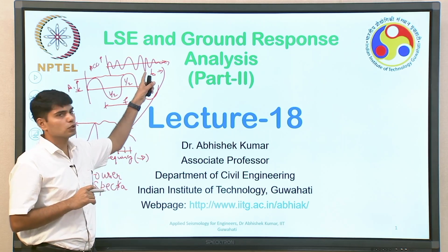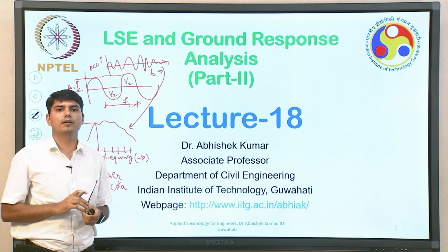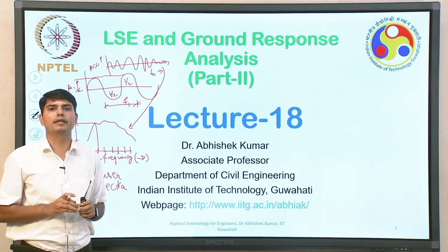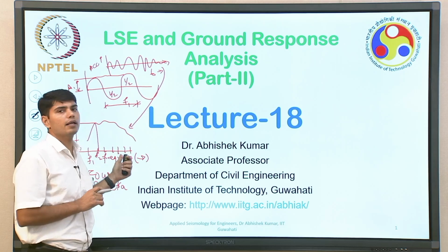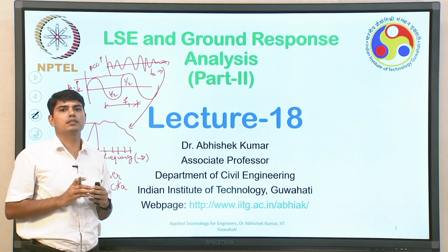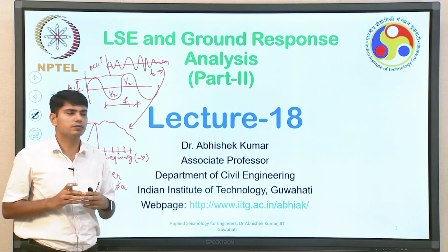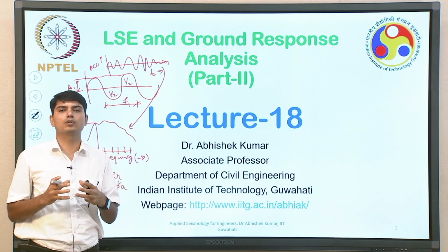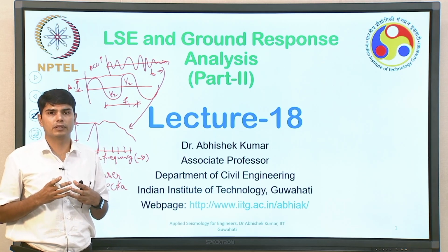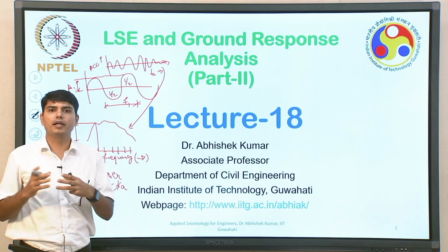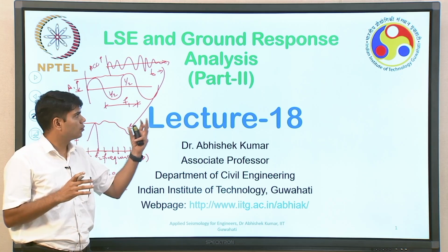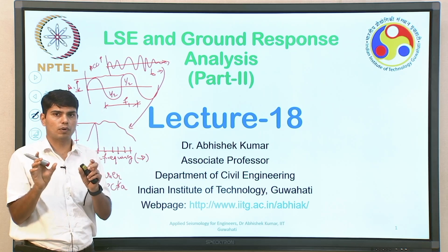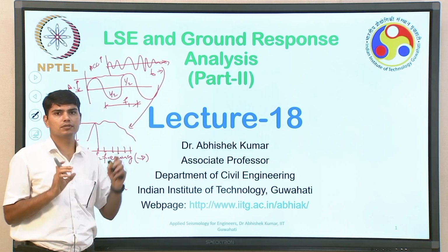When we are talking about motion in terms of variation with respect to time, we generally refer to it as the time domain. When we are talking specifically about the frequency content of the motion, as given in terms of Fourier spectra, we often refer to it as the frequency domain. So, dealing with ground motions or performing ground response analysis, often we will talk about two terms: one is time domain, the other is frequency domain.